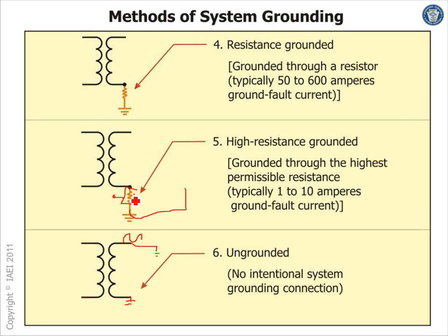In the US, we use resistance grounding, high resistance and low resistance, on the high voltage system. That's my experience with it, on 13.8 and 4160. We also use reactance, but I'm not sure if they use it there or not. But I know here in the US we use reactance and resistance, high and low. I guess that's one of the problems with deep grounding, so you spend more time on it. Okay, so yeah, that would be the way.